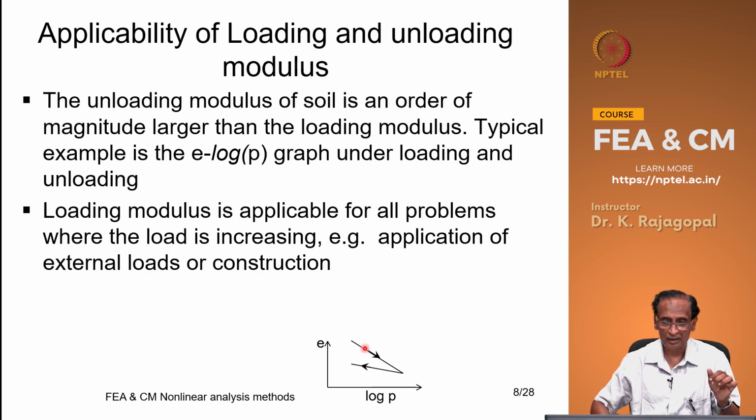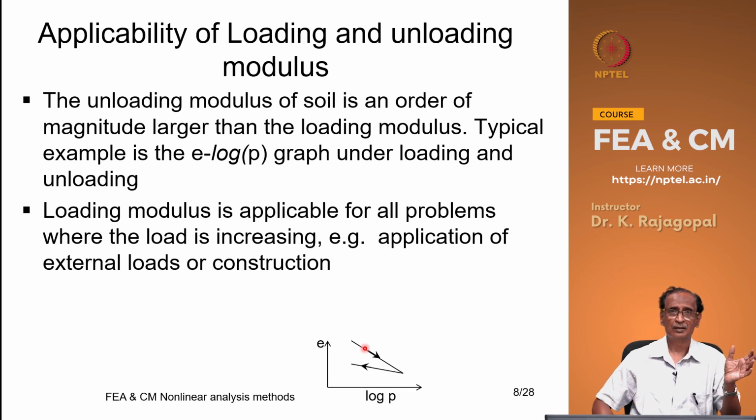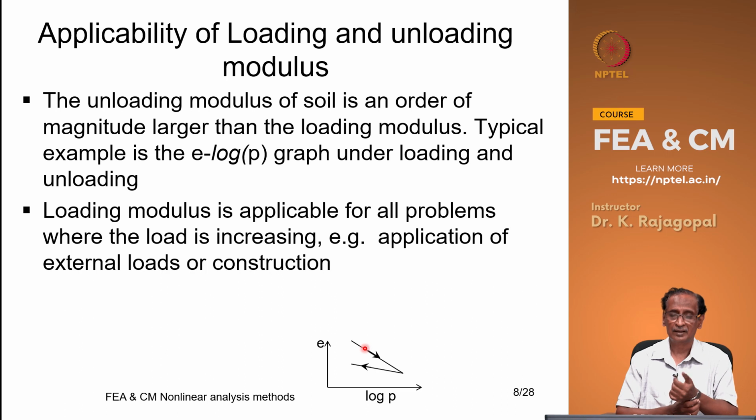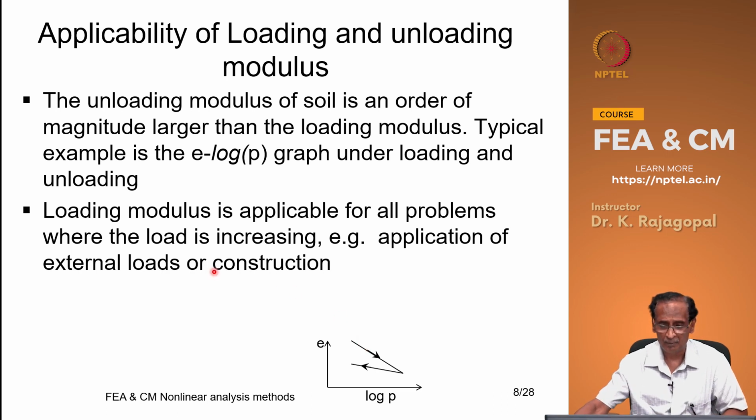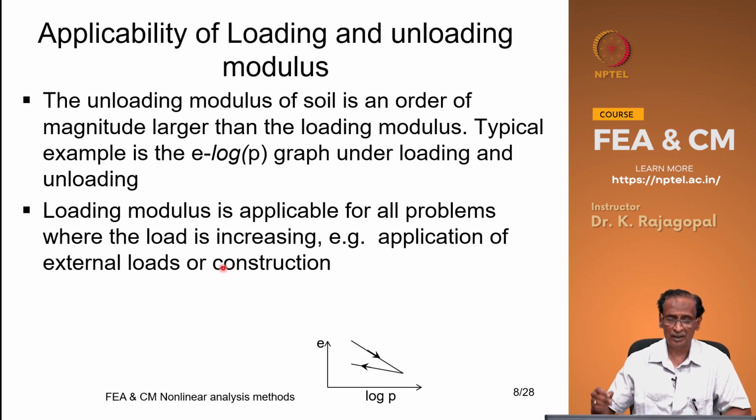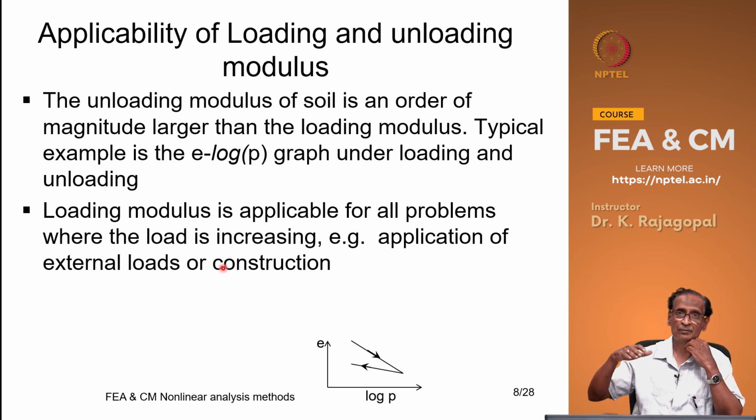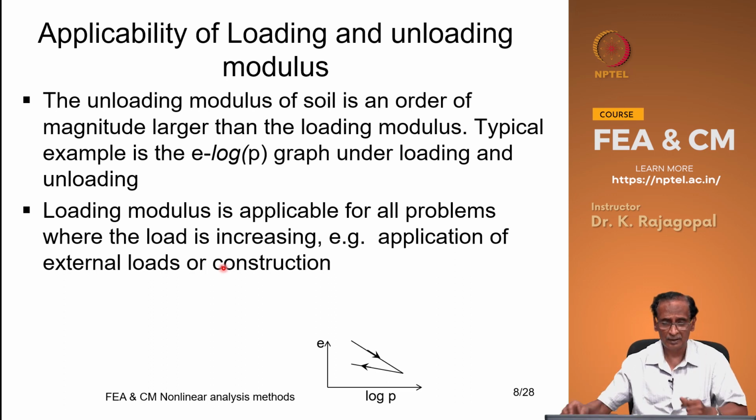And so the loading modulus, the typical Young's modulus that we define, is applicable for all the problems where the load is increasing, like our construction or our gradually placing the soil during the embankment construction, that we can simulate with our loading modulus.